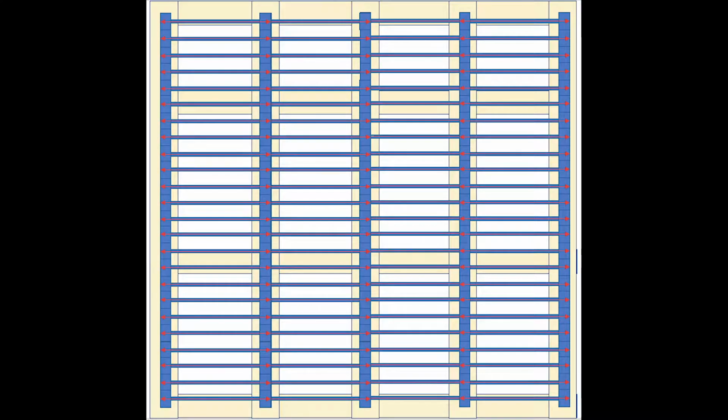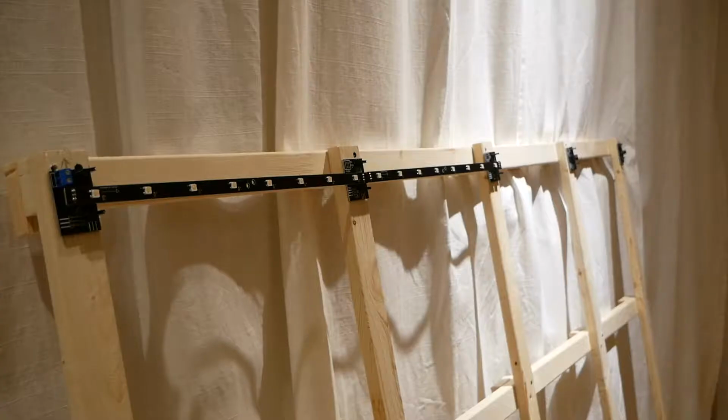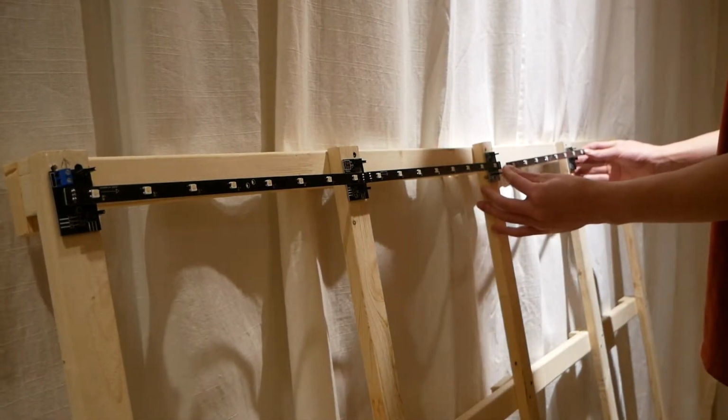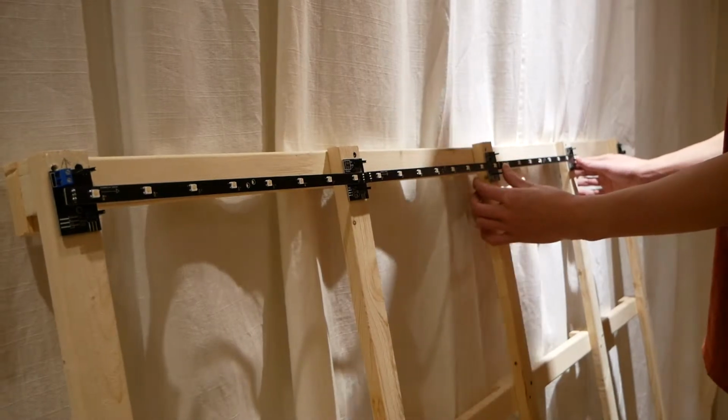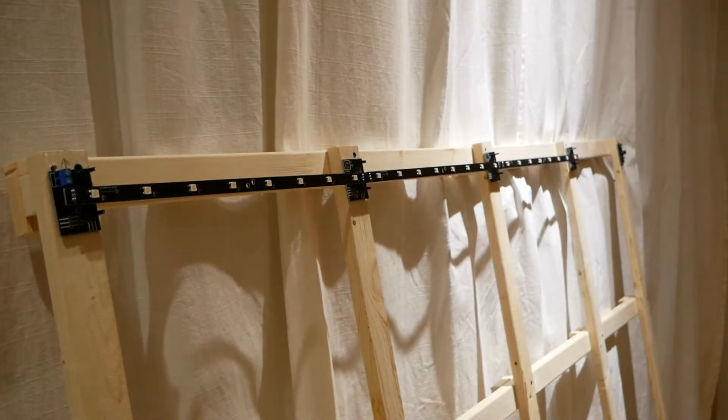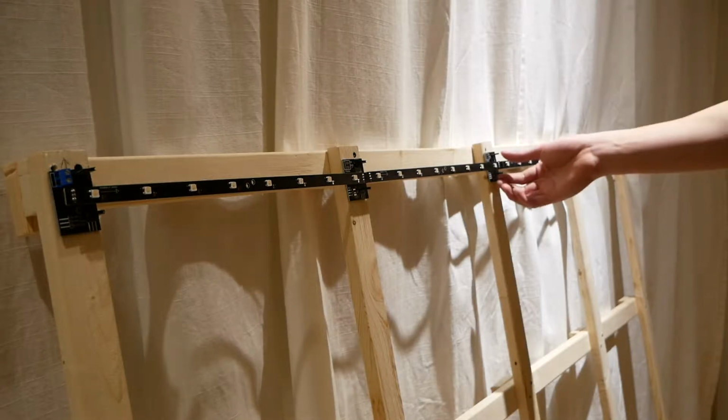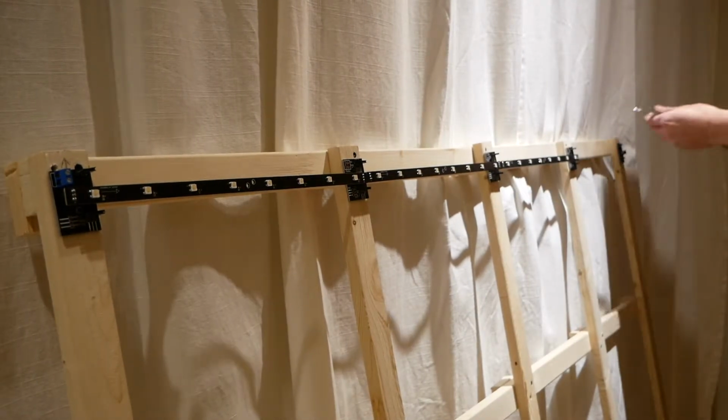Afterwards, I began creating a matrix design that's modular and relatively simple and cheap for a large RGBW wall. It's similar to BitLooney's own wall, but uses thin strips of 8 LEDs and connectors for each strip instead, which allows for a variety of matrix sizes to be created. The size of the strips also saves money on PCB shipping and manufacturing costs as opposed to large matrix panels.